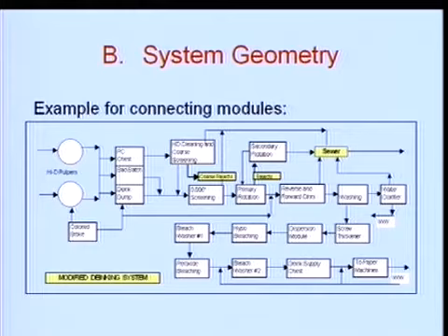So here you can see I have started out with the high density pulpers, some chests, and going to coarse screening and cleaning, then fine screening, flotation, cleaning, and washing. And washing, remember, always has to be accompanied with water clarification so that you can recycle some of the water back.